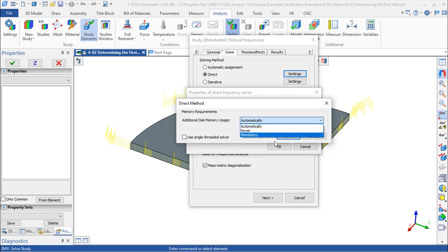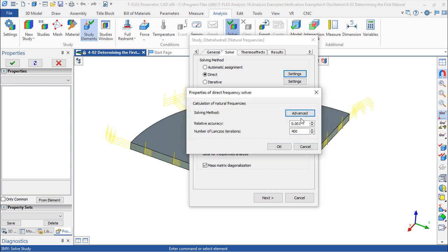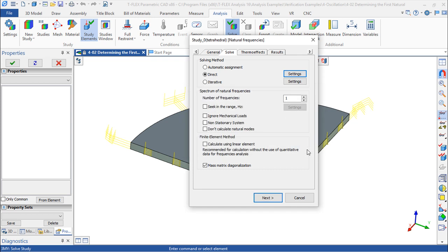So we have a couple of choices. And we've seen this also in previous videos because the options were the same. So accuracy and iterations. If you define a higher number of iterations, it will take more time. And the accuracy will be the tolerance to reach a result.